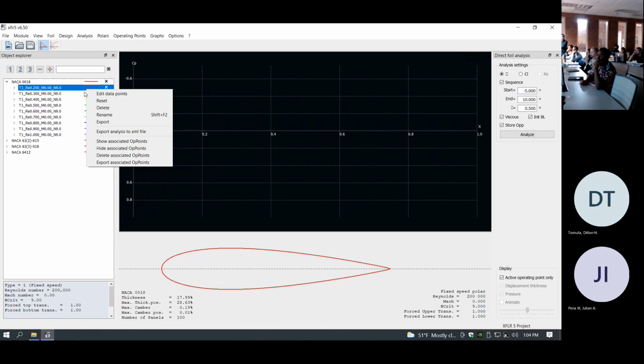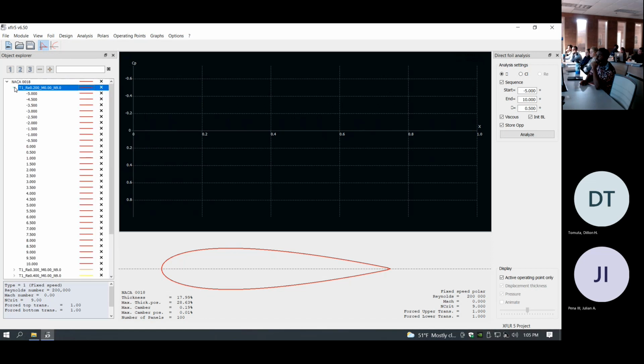Unfortunately, it is not here, but if you did want to change the color, you would click on the little colored bar here, you would right-click, and a little menu pops up that says style. You can change the color, the marker size, the width, the design pattern, things like that. But that's essentially how you do it. It's not on this one, unfortunately. I did it on version 6.53, this is version 6.50.